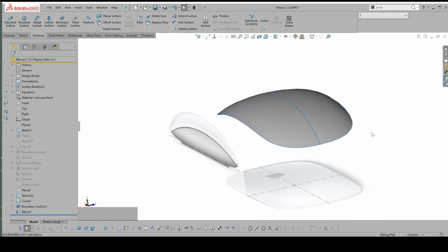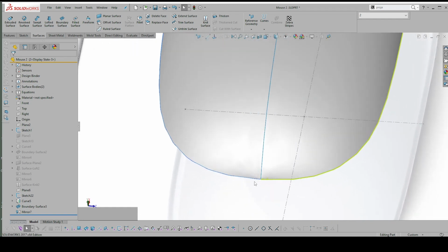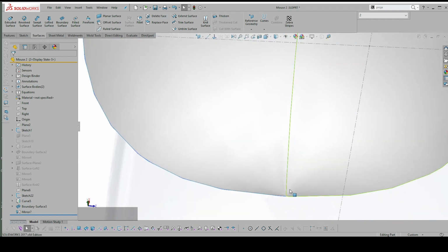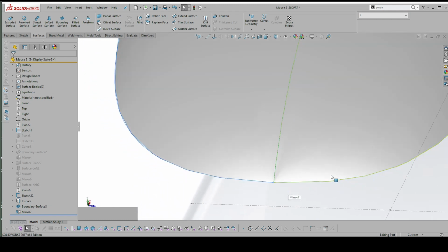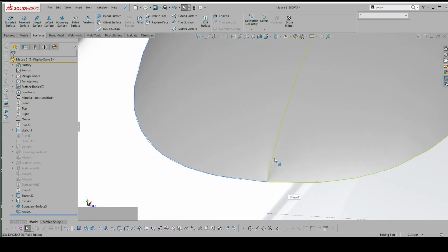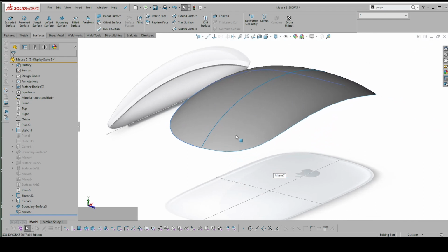Now we'll create the underside. Let's just make sure this is... So you can see there's a little bit of pinching here, right? So the way to get rid of that would be to actually break this line up into separate pieces, because you've got triangulation happening in this corner, which is not great modeling. I might make a video just to show you how to get rid of it.